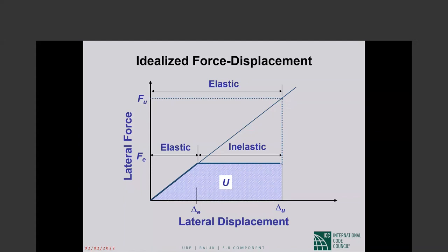The big difference, obviously, is that much of the total displacement in the second case is inelastic. Now, this inelastic displacement has to be limited to values where they do not cause collapse of the structure. That's the first thing. Okay, so we will allow inelastic displacements, but not to the extent that the inelastic displacements will cause collapse of our structure.